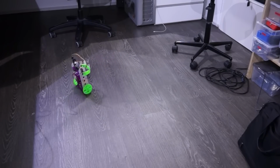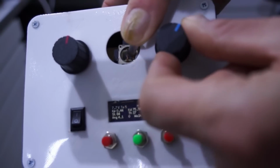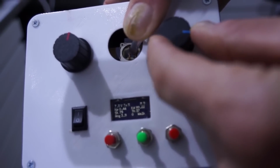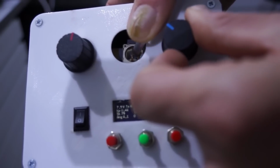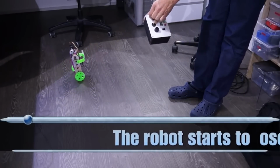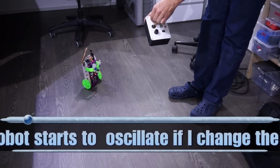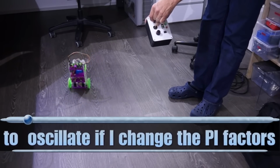Usually I use potentiometers or rotary encoders to adjust these factors and see the result real time, as I did with my robot. By the way, in this robot you find two independent PI controllers. One to keep the angle upright and the other to stabilize speed. But more about that in a later video.